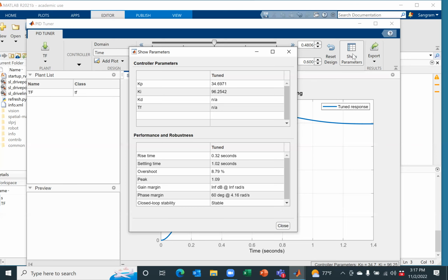Linear system stability is dictated by the eigenvalues of the system. Eigenvalues are the poles of the transfer function, and the poles of the transfer function are where the transfer function becomes 1 divided by 0, which becomes infinity. As long as the eigenvalues are on the left-hand side of the imaginary plane, things are fantastic. As soon as they are on the imaginary axis, things are okay, but not bad. But as soon as they cross the imaginary axis, the system becomes unstable.